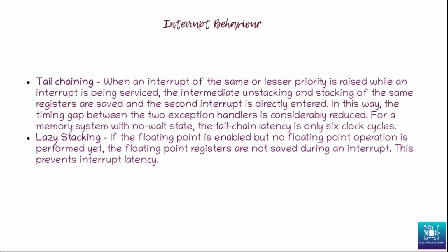Now, between these two interrupts, once an interrupt completes its execution, there is an unstacking process that happens. The stack frame is restored. Whatever stack frame was saved before the interrupt execution is restored back into the registers. Now, if another interrupt comes in, of the same or lesser priority, because if it were of a higher priority, then there has to be a preemption and stacking of the second interrupt. But this is a different scenario.